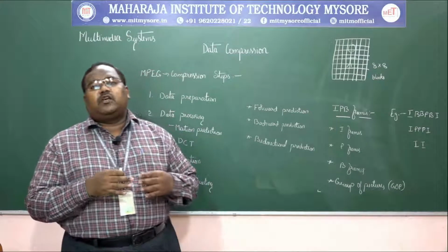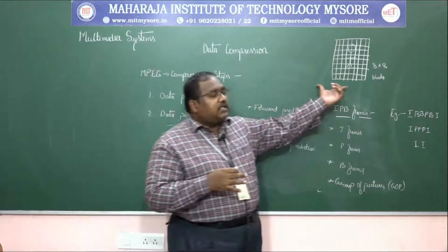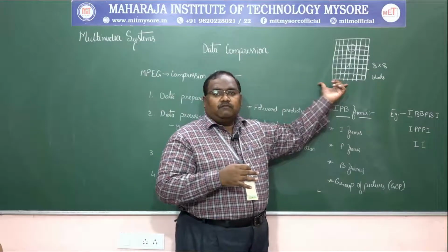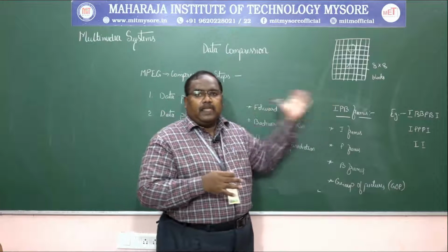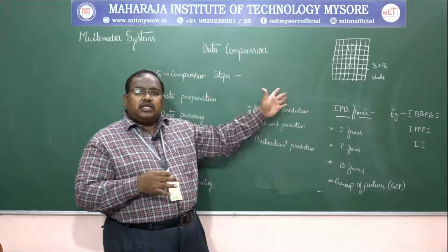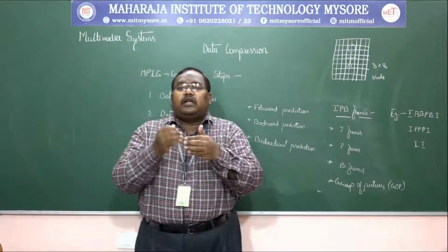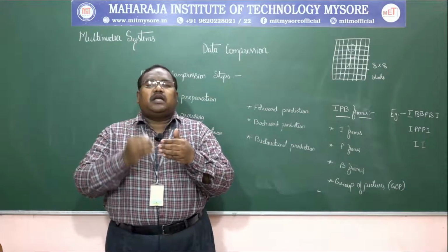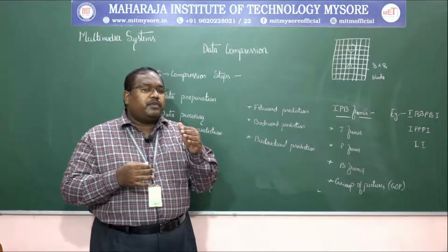In other words, we apply DCT on these 8x8 blocks, because in the first stage we have prepared, in the second stage predictions are made, and now we apply the DCT transformation on these blocks. The DC component consists of lower, or sometimes constant, frequency components. Why constant?